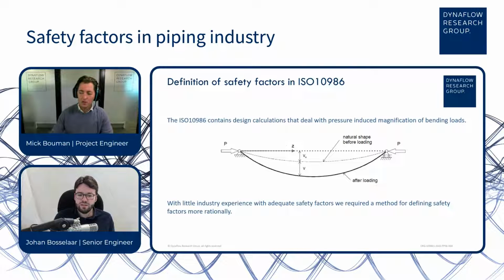Because do you have like a pressure dependent safety factor or something like that? It isn't a pressure dependent safety factor, but depending on the allowable pressure, the safety factor of the bending moment had to be defined, or the other way around. So there was a lot of intercommunication necessarily, and we couldn't think of a way how to do that purely based on our intuition. So we had to use a more rational framework.